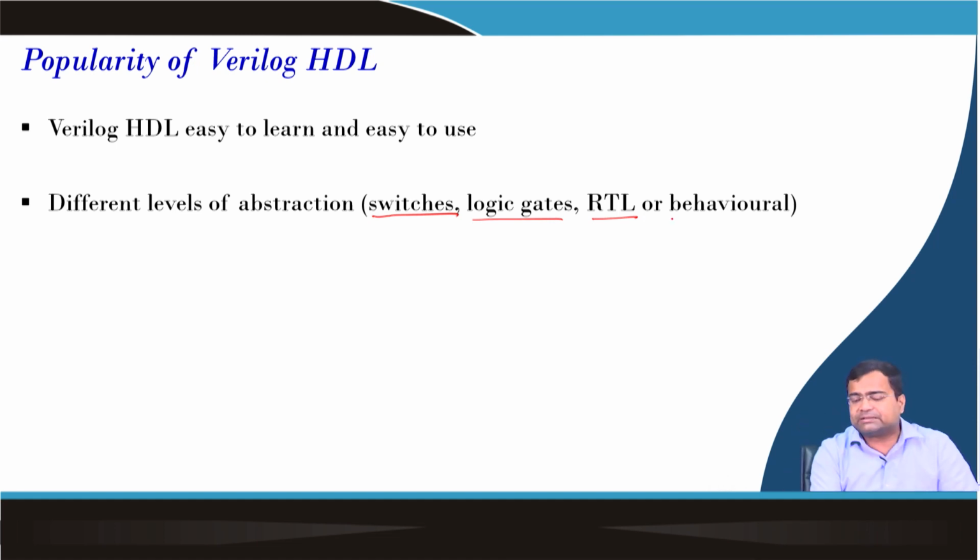Or you can also expand, and this is particularly for data flow modeling, where you write in terms of how various logic blocks are connected to make a complete circuit. Or you can represent it at the behavioral level, particularly if you are talking about an if-else statement, or you want to make a clock synchronized operation, like a synchronous one, or you want to implement a finite state machine. So, this can be a behavioral model.